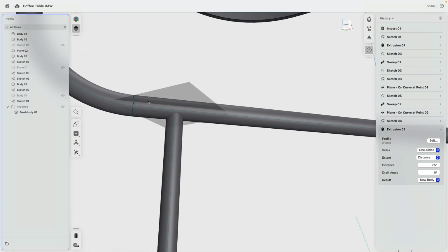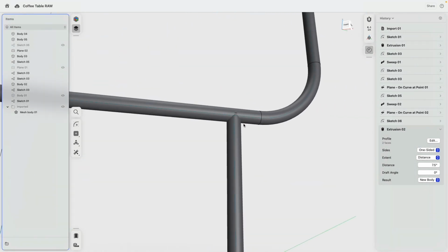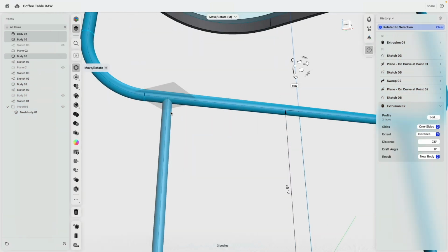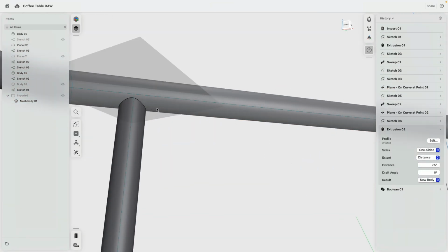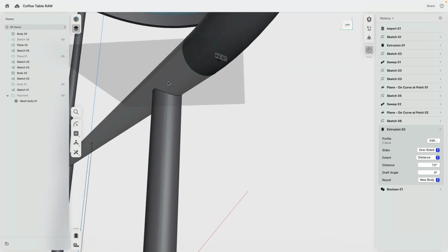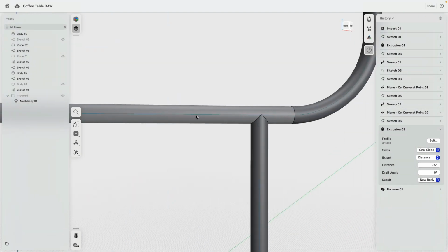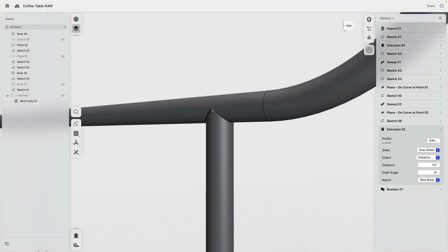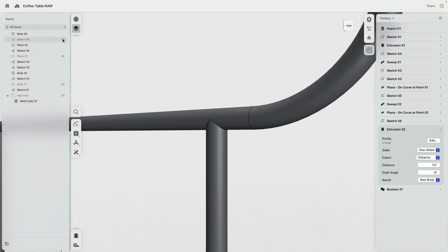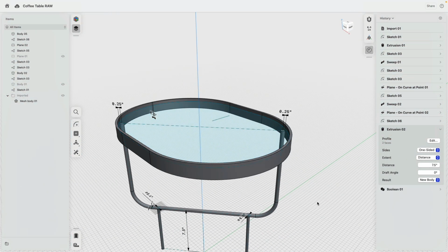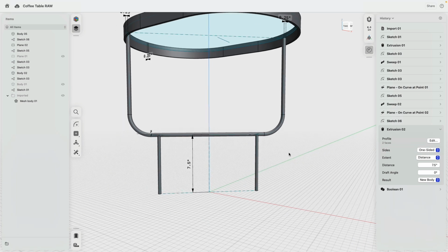So what did I do? A pipe 0.4 and 0.5. You see, when we join all those together, you see here how the smaller pipe sits perfectly on the bigger pipe. We could grind this one out, weld it on it. When they have the same diameter, this is a much more complicated joinery. So this one here, we also say 0.4. Okay. Actually also makes the legs a tick thinner.